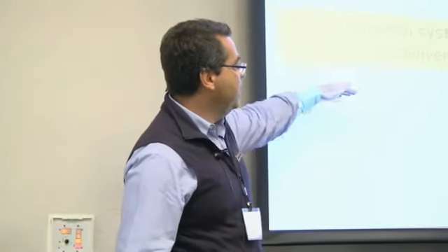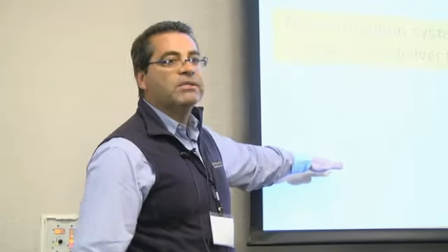But anyway, so again, the criteria, I would say, suggests 16 to 20 hours, but the industry designs 20 to 24 hours. So to apply that amount within the period of 20 to 24 hours. Okay? And your time for irrigation comes from the maximum amount of water that you have to apply divided by the application rate. So how many inches per hour?